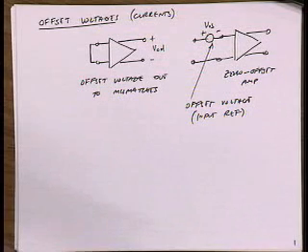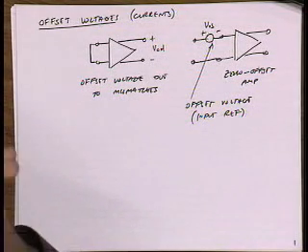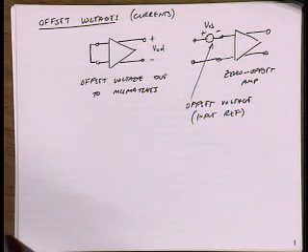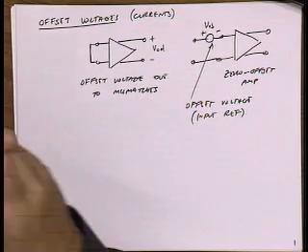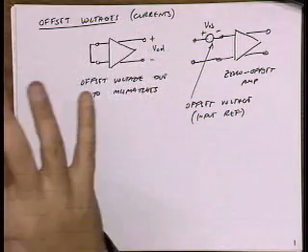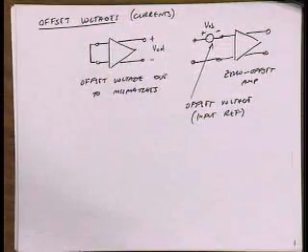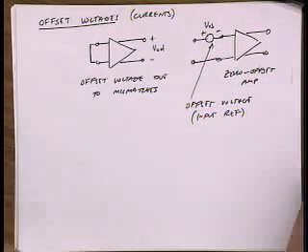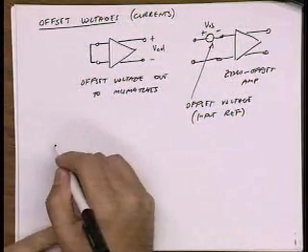Make the input devices larger. Yeah, from a device perspective, we could always go in there and get better matching and pump up the currents or bias the thing, and we'll talk about that today. But at some level, you're going to be left with some residual offset. So how do you deal with that? For example, some op amps like the OP07 use some resistance they can change off chip. Yeah. So we could actually trim the offset.